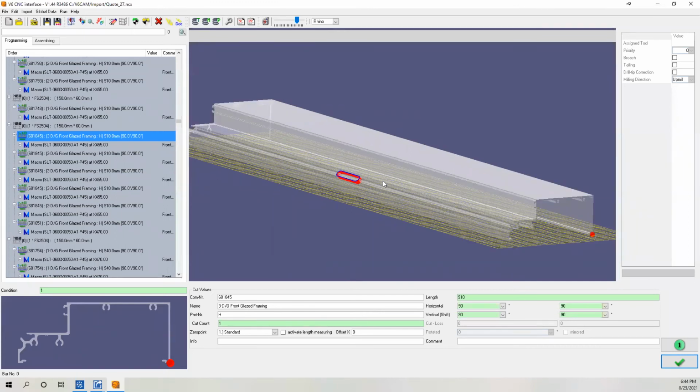You can do changes here on your machining for that particular milling. Once you change that and save it, next time you send the same profile, it will automatically recognize that particular milling on that same profile and automatically put the new holes. Let's say the hole diameter was 5 millimeter and you want to change that to 6 millimeter. You could do that here, and then the next job automatically will come as 6 millimeter.